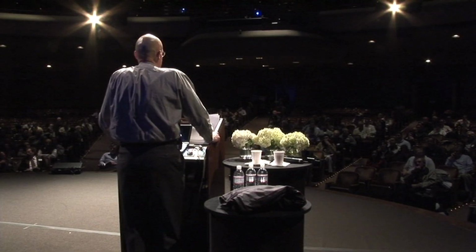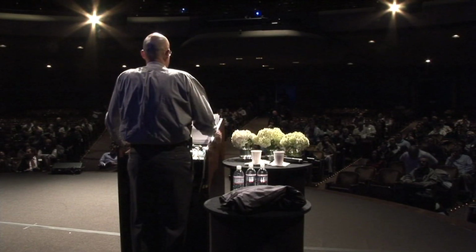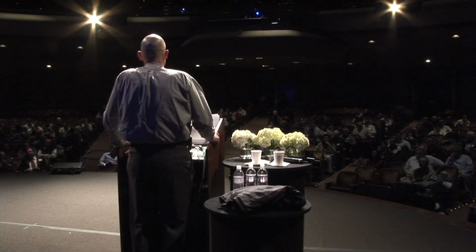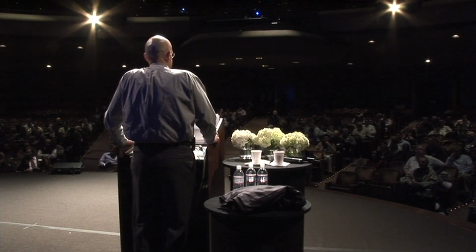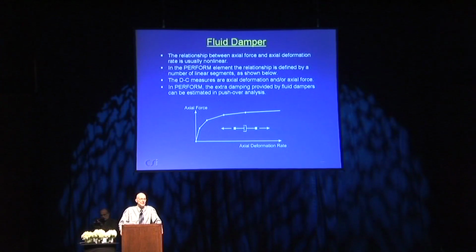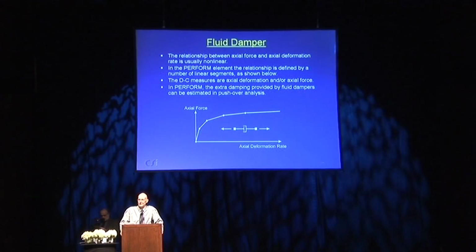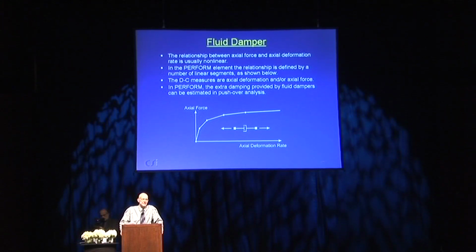And incidentally, if you do a pushover analysis, there's no dynamic effect, and so if you have a fluid damper, it doesn't do anything. It has no stiffness in the pushover analysis. But Perform does have a little feature where you can estimate the extra damping which is provided by fluid dampers. Even though the pushover analysis doesn't have any strength from the fluid dampers, it has an approximate method which will estimate the energy dissipation in those fluid dampers and give you some rough idea of how much additional damping you would get.